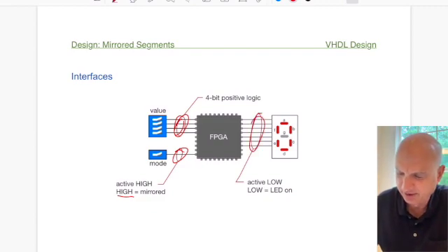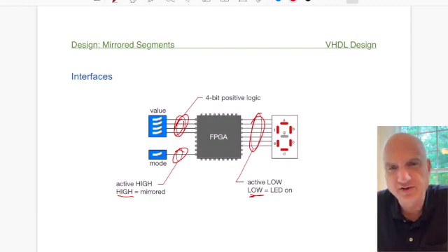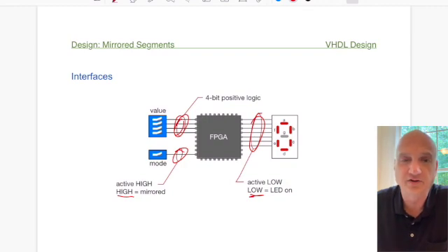And here, the 7-segment display basically shows you that you have an active low, and that means a low means the LED is on. This is not unusual in some LEDs because of the way they're made to have a low activate the LED in a 7-segment display. So it's a little different than we're used to maybe with an LED, which you light with a high, but it all depends electrically on how it's connected to the port pin. And that can vary depending on a variety of reasons.